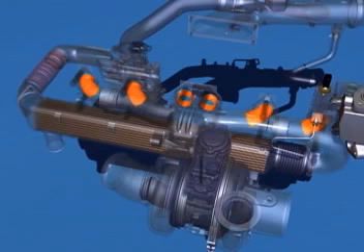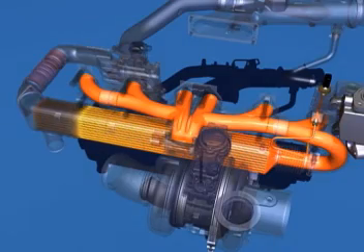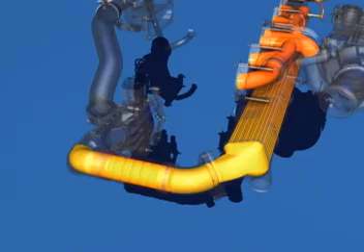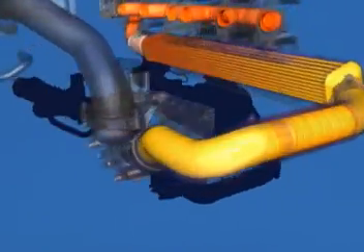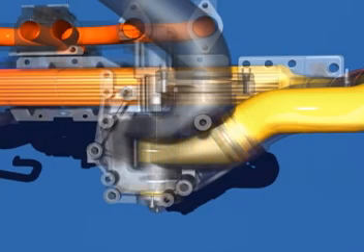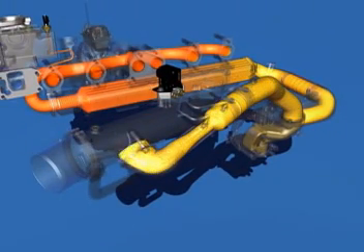Pressure inside the exhaust manifold is increased. This is accomplished through the use of a variable geometry turbocharger, an exhaust throttle orifice, or other restrictions. The recirculated exhaust gas enters the water-cooled EGR cooler from the exhaust manifold, where its temperature is reduced. The cooled gas then continues to flow through the exhaust tubing to the EGR valve. When commanded to do so, the EGR valve opens and allows more exhaust gas to flow. The gas then flows through the EGR connection tubing toward the intake air inlet.